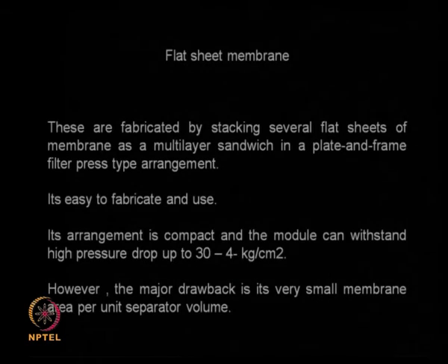So the fabrication and setting up of my membrane unit is easy, but the major drawback is my surface area per separator volume will be very less. So it is not good enough. I may have to put several stacks of plate and frame design. That is the main disadvantage of flat sheet membrane.